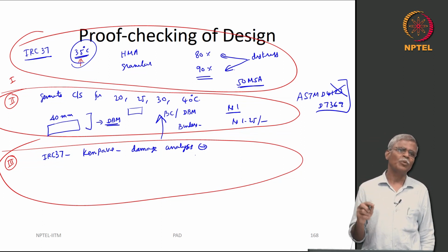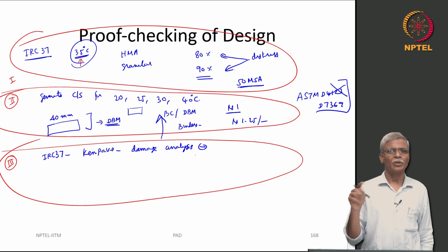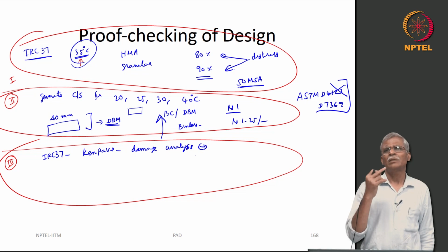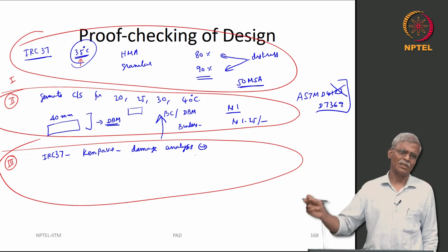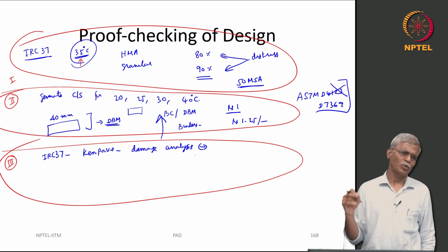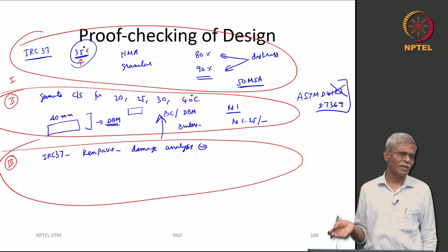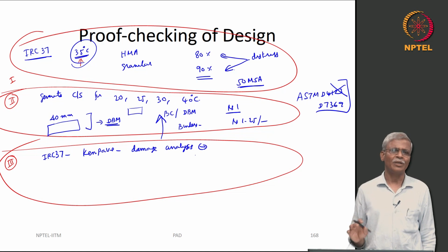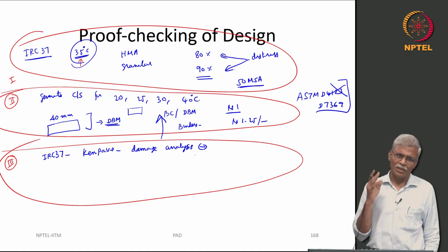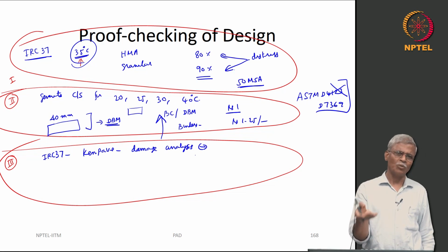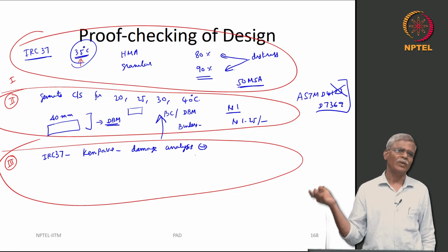They want you to input the material properties for 12 months. Can it be done? We will assume that as the temperature increases and decreases, the modulus values also vary in one particular way. Again, some of my publications have this kind of data, you can take a look at it and use it. And then, based on the input that you got from the previous one about traffic, you will have monthly variations.